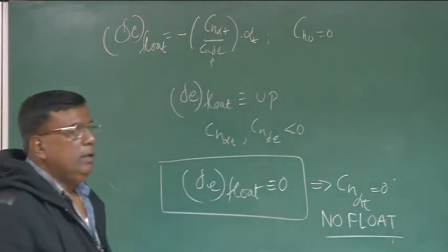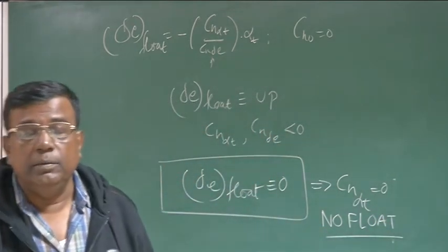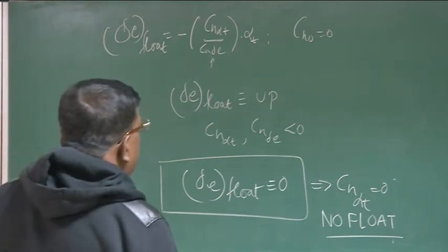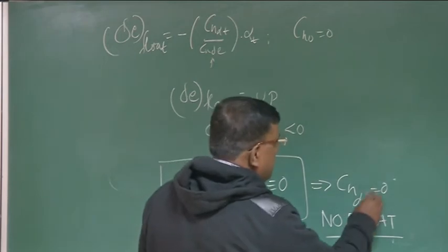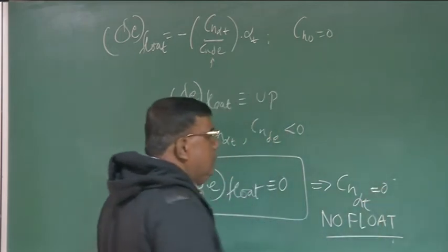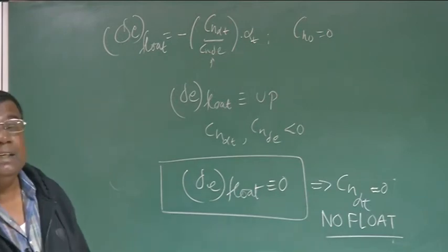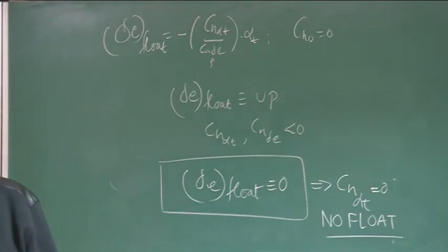This should be in your mind. You will understand why I am mentioning this at this point, right? And how can you make CH alpha T 0? One should give a thought to it. If the hinge line and the resultant of the center of pressure are at the same point, then theoretically CH alpha T should become 0.